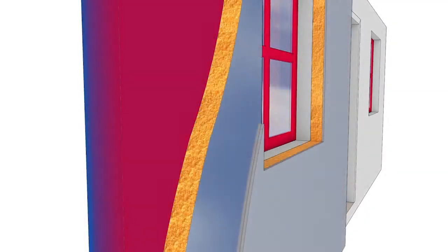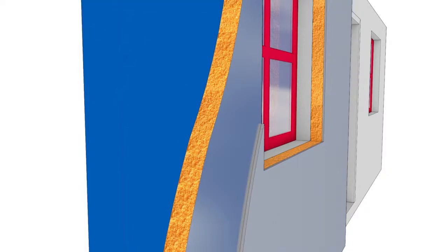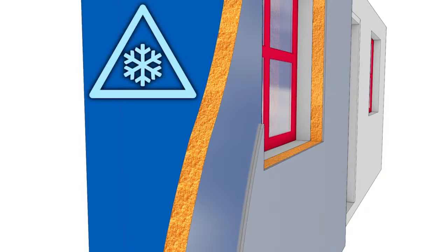Firstly, adding insulation of any type will reduce the temperature of the existing wall masonry, making it more likely that condensation will occur, and will occur further to the inside as there will be less heat penetrating from the living spaces to heat up the masonry. Secondly, some insulation types such as rigid foams can prevent the drying out of condensed moisture inwards into the building, further compounding the problems. If not properly accounted for in the design, this moisture accumulation can continue unchecked, leading to increasing problems with damp and mould over time, and in extreme cases, causing the masonry to degrade due to freeze-thaw cycling.